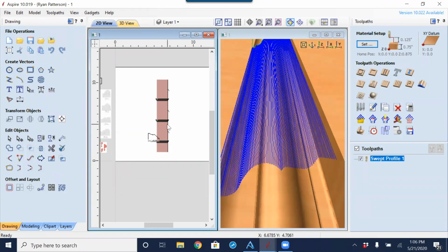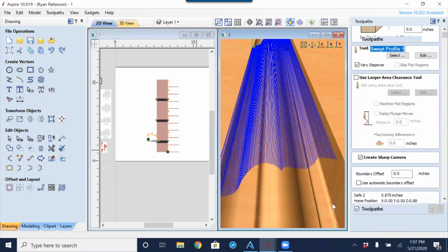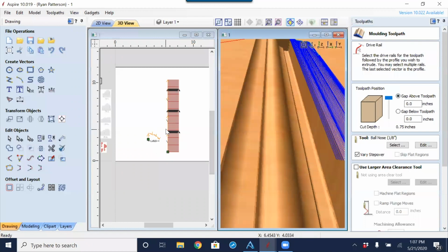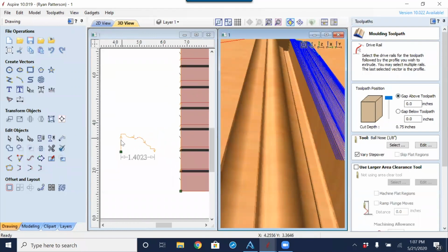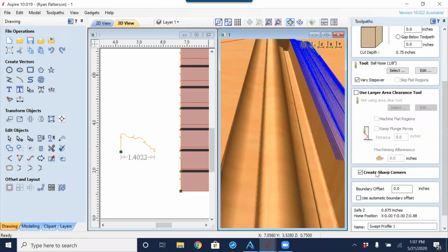And to do that, I just went into Node Edit, hovered my mouse over top of that node and selected the letter P. And yeah, sure enough, there. So it is going to be offset to the left now. So that is what these lines are indicating, the direction of the path that's going to start. We can see that the arrow is starting from the green start point. So basically what is happening here is the green dots are kind of matching up to one another and extruding it along this line.